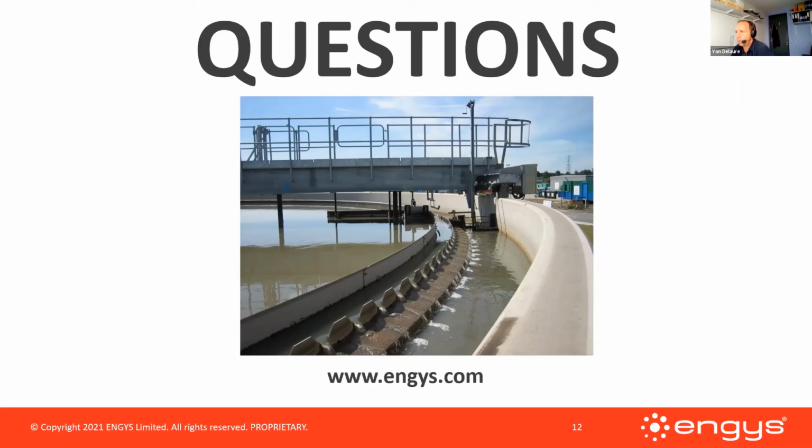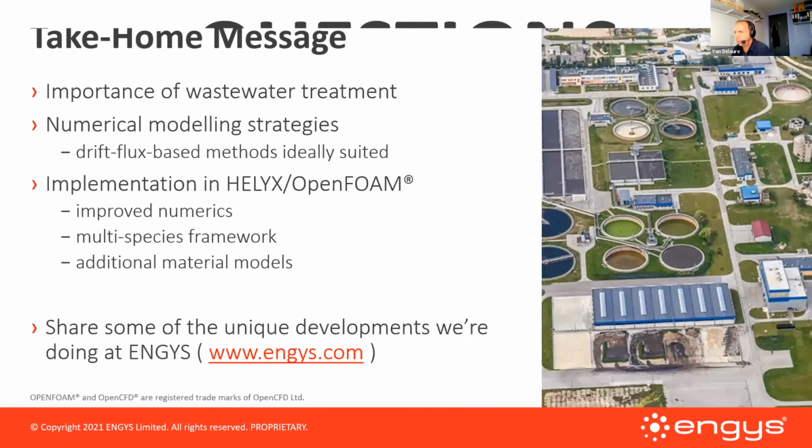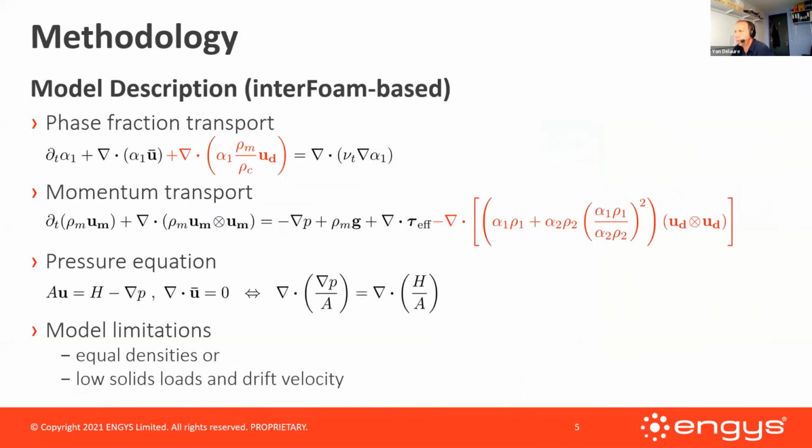He says, thanks for pointing out the inconsistency regarding the barycentric and volumetric mixture velocities both used. Have you used the drift flux for closure of the phase relative velocity? Well, the drift flux is inherently given, and I'm using the formulation as is. I'm currently also testing the correct formulation, which would be either using the barycentric velocity throughout, getting you an additional pressure term in the pressure equation, or using the volumetric velocity, so formulating the momentum equation in terms of the volumetric velocity, which gives additional drift flux terms. I've tested both, so yes, they're taken into account fully.